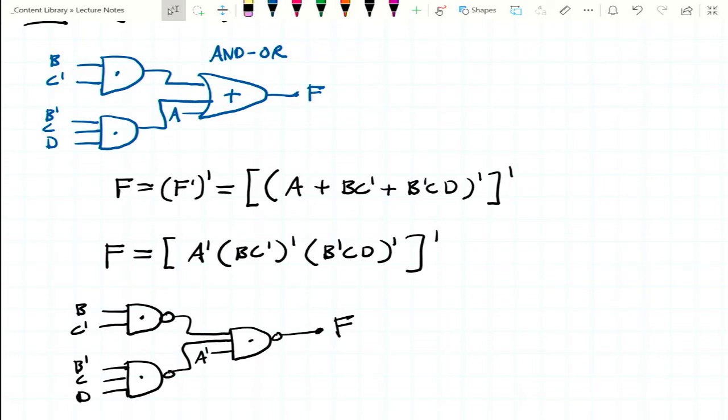We started with our two-level AND-OR circuit. We replaced all of the gates with NAND gates. And then we left these literals the same. We had a single literal, the A, that was an input to the output gate, that last OR gate, which became the input to the output NAND gate. That one gets inverted, but the rest of these stay the same. So that's the process.